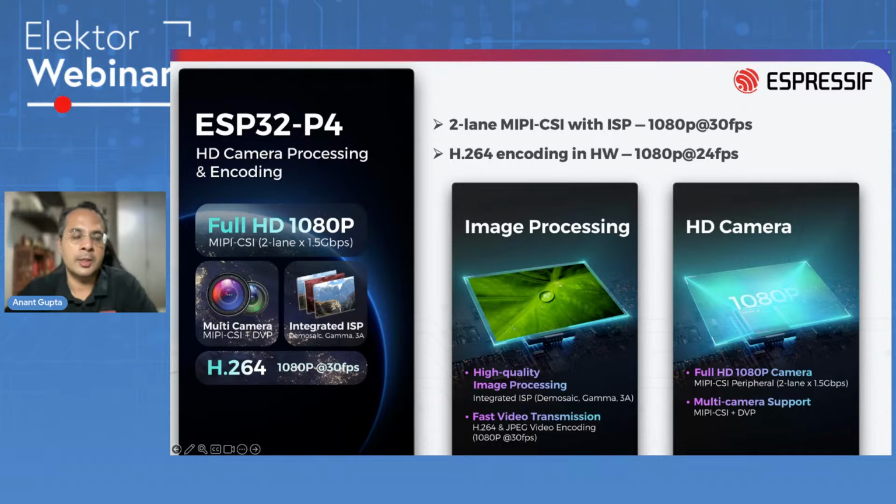Next, we will talk about the HMI capabilities. So basically, the ESP32-P4 has HD camera processing and encoding. It has a 2-lane MIPI CSI with ISP, which can support up to 1080p at 30 frames per second. Additionally, a very important feature, I believe, is the H264 encoding in hardware. And that can do right now 1080p at 24 frames per second.